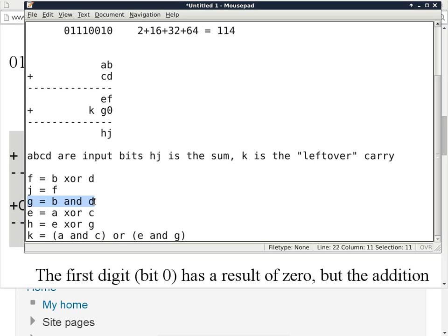When you look at the individual half adder, this is an input pin, that's an input pin, this is an output pin, this is an output pin. What you need to do is to first define what a half adder is as a component, turn it into a component, and use half adders to make a full adder. Once you have a full adder, turn that into a component, and then use that to make a 4-bit by 4-bit adder, which is really just slapping things together and drawing wires.